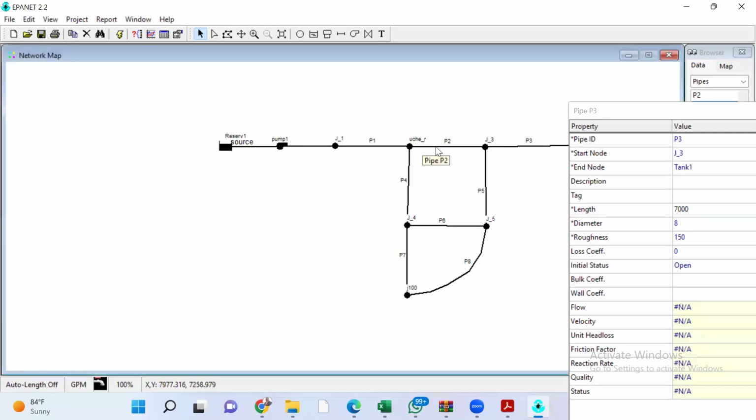I'm done. Who is done, please? Sir, I have a question, sir. Go ahead. Sorry that I will just take you back a little. But don't take it too far. Anything you don't understand, remember there's a video backup. Yes, it's okay. The pump, sir, you said that the difference in the elevation is what will determine the size of the pump? Yes. Because you need water to pump to the tank. And the pump starts at 830, while you are standing at 700. So you need something of 130 to push it up there, without frictional losses anyway. Okay, thank you.